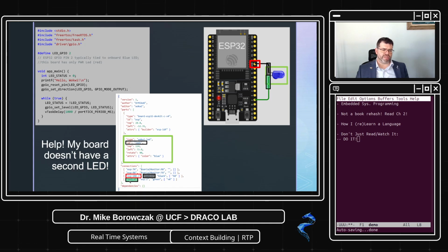The anode side of the LED, and notice it says LED1 here, LED1, LED1, right? LED anode side, what is that connected to? Well, this is the ESP device, pin 2. There you go, ESP pin 2. Why did we choose pin 2? Because in our code, we have connected to LED GPIO, general purpose input output 2. So you'll notice all 3 of those match up. Change any one of these, right? Change this to 4, for example, and see what happens to your code. Does it still work?